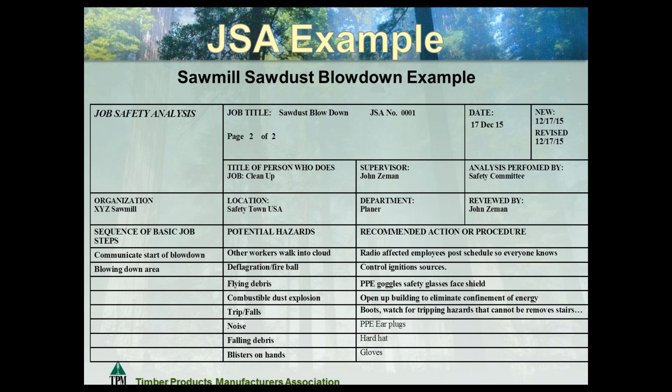Well, how do we control that hazard? If we knock out the legs from the table, number one, by starting with ignition sources. You can't have a fireball if there's no ignition source. So we want to go around and make sure that we don't have any bad wiring, any welding, any hot bearings. Use maybe a temperature gun to look for hot sources over 400 degrees.